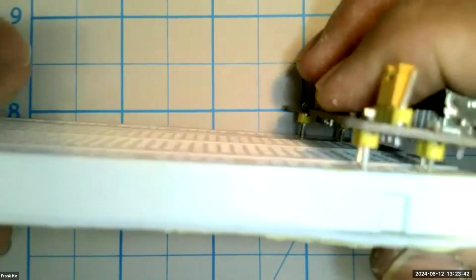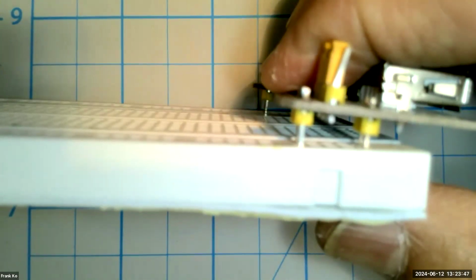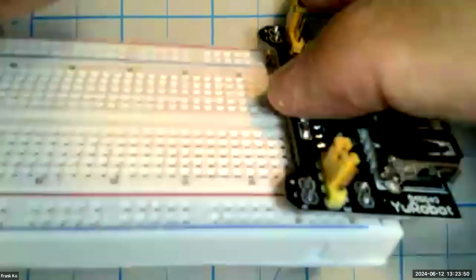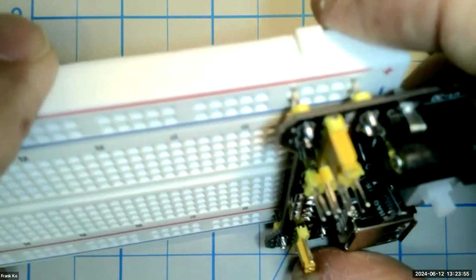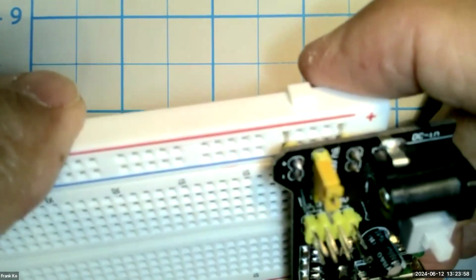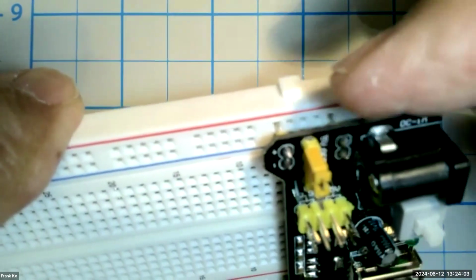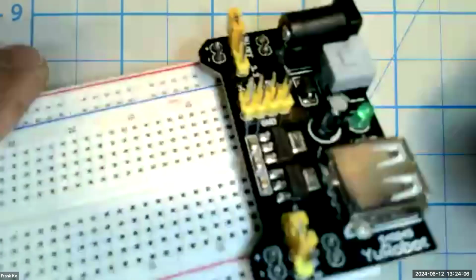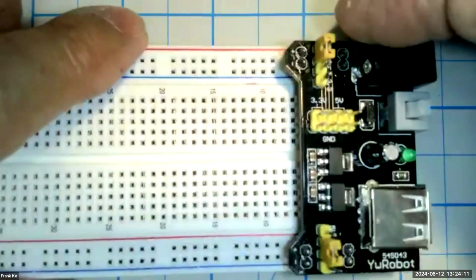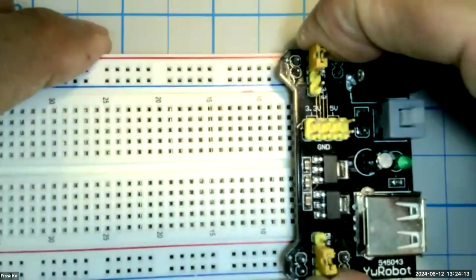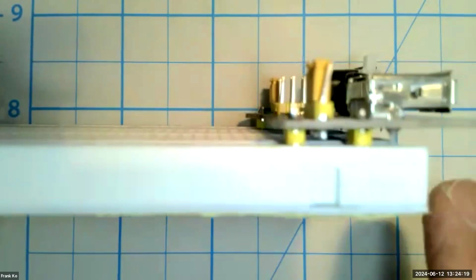You're going to need to look at these pins very closely and confirm that, yes, they are about ready to be pushed down in. Don't press down until all 8 pins are correctly into their corresponding holes, all right? Because the last thing you want to do is to press down and actually damage any of the pins. Once you have the confidence that the 4 pins on the 5-volt side and the 4 pins on the off side are properly positioned, then and only then push this down firmly, and you can see that is the end result.